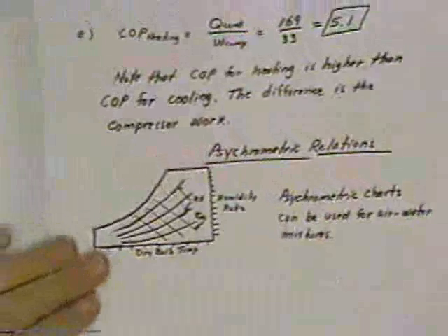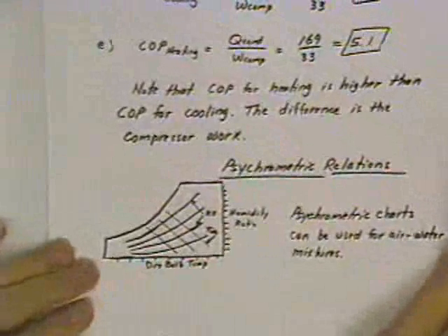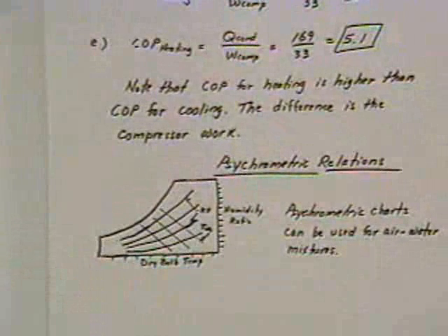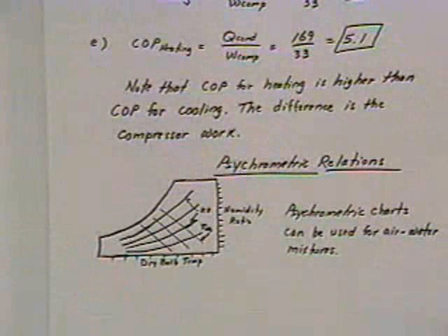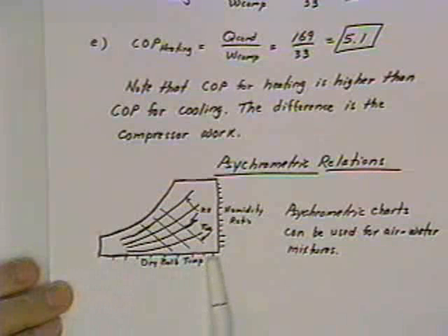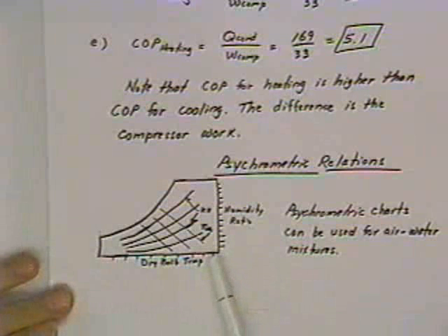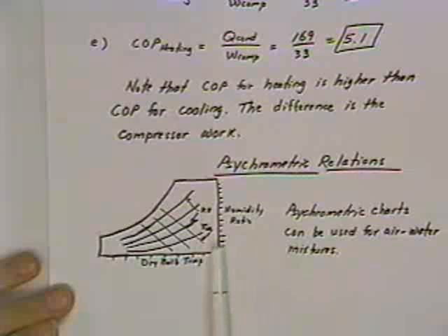First of all, I've got a psychrometric chart sketched here, and I've got a copy of the one out of our textbook. But before we get into the much more complicated one in the supplied reference manual, I'd like to acquaint you with what's on it. The psychrometric chart is set up in terms of dry bulb temperature, which is just the ordinary temperature that you have outside or inside the room. So it's a hot day, it's 95 degrees outside, the weatherman always reports dry bulb temperature.